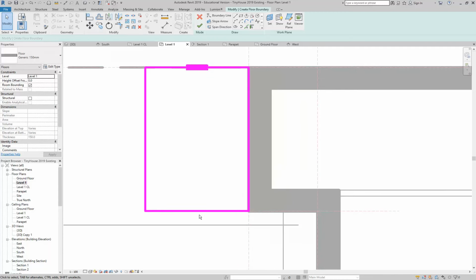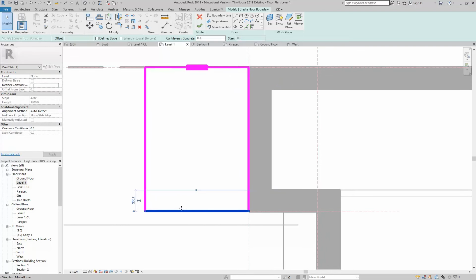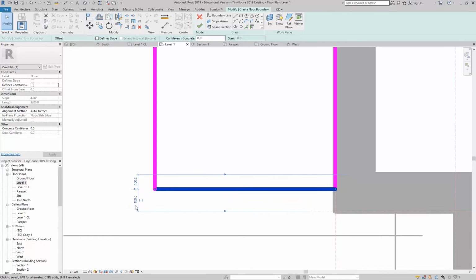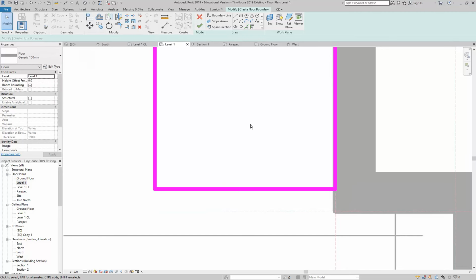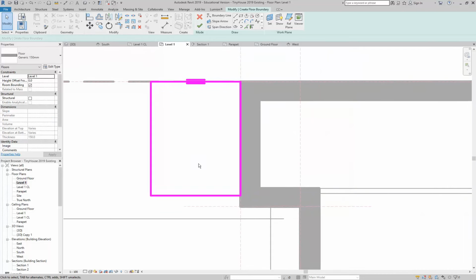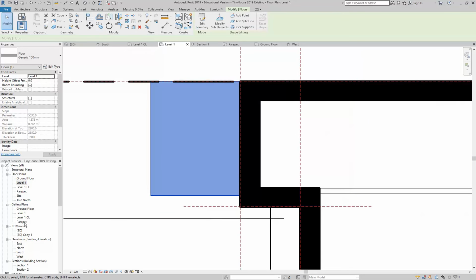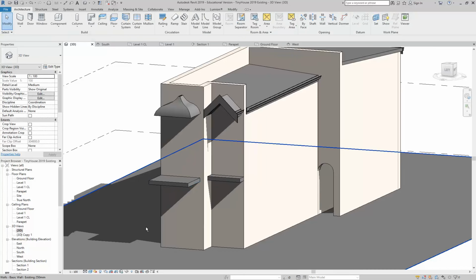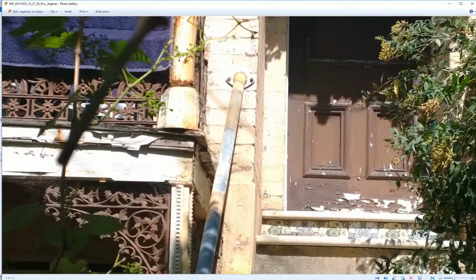And then to get this edge to measure from the wall, the trick is to select it and just drag it a little bit above, so that you then get the measurement or the dimension there that you can adjust. So again, it's about 150, brick and a half roughly, from the corner. So I'll finish it there and just show you then what it's looking like in 3D. So those two little floors make a big difference to give you an idea how the elevation works.